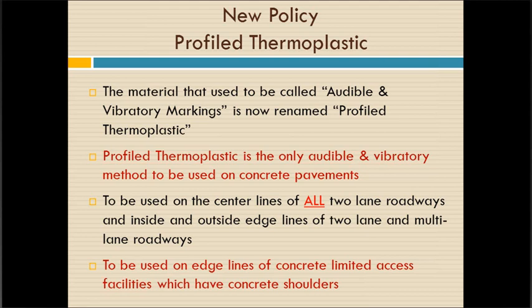The pavement marking people did not want us to be grinding on concrete because of the effect on expansion joints. So if you look at 518, you'll notice that on concrete pavements with asphaltic shoulders, we've moved the rumble stripe, the rumble strip, over onto the asphalt.